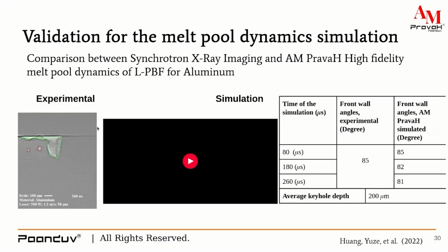So when the process parameters are varied for different feed rates, you can see the liquid mode transfer changes completely from droplet transfer to continuous liquid transfer, and that we have also observed in the simulations that we have performed.